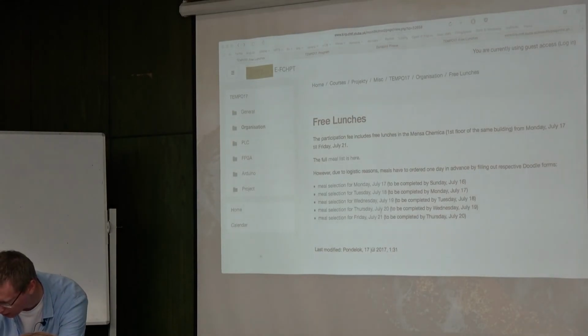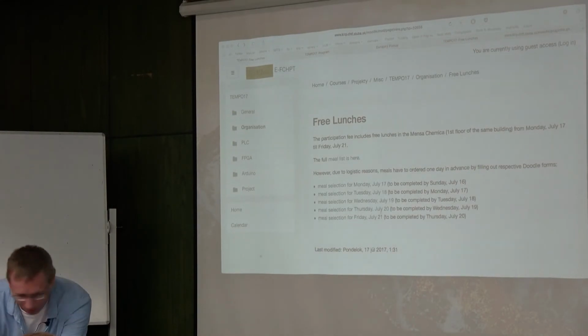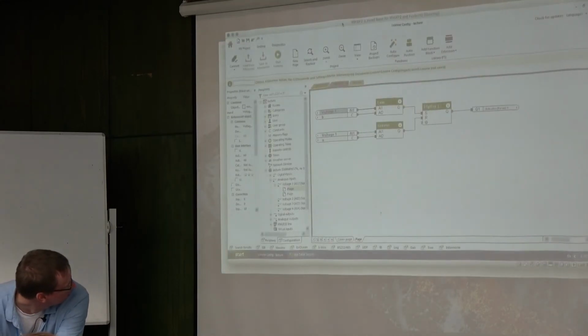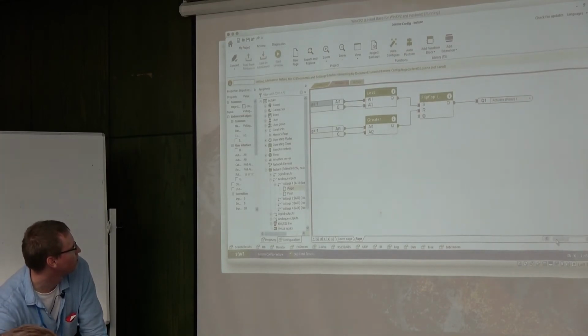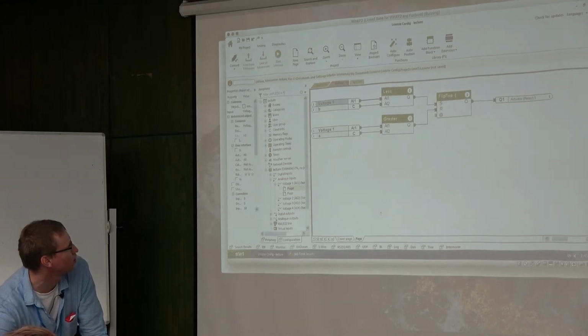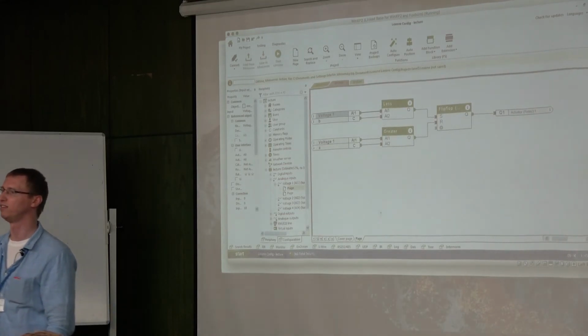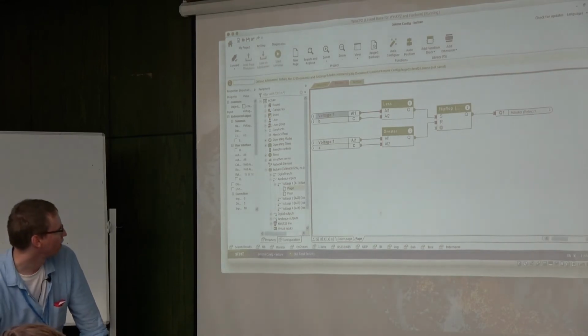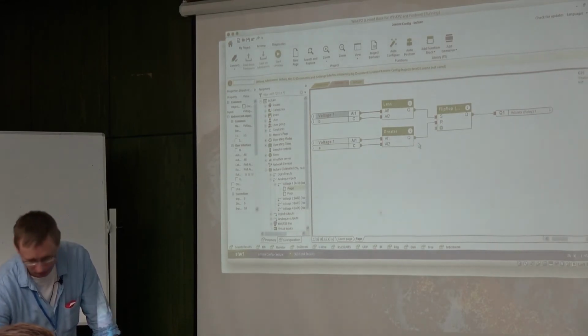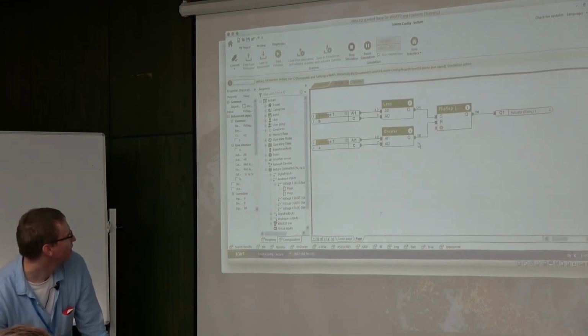So let me show you also how it works, so that you get a teaser of the exercises. Let me switch this here. Hopefully everything will be visible. Okay, so that's the environment that we will use for the exercises. The advantage here is that it's a complete simulation of a PLC. And here I have to warn you, the vast majority, if not all of those PLCs, only support Windows. That's the sad reality. They have arguments for that, and that's what we have to accommodate for. So I'm running it in a virtual machine.